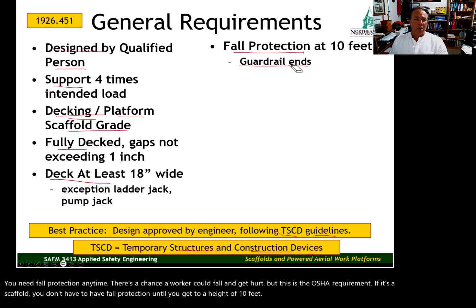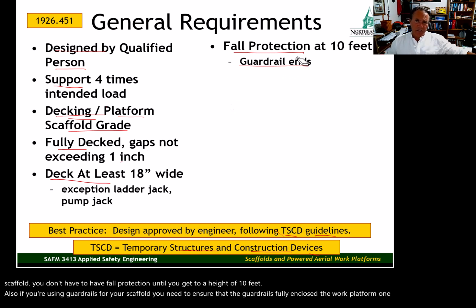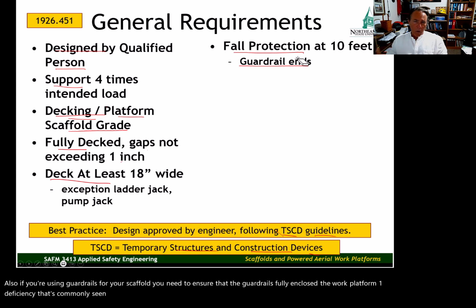Also, if you're using guardrails for your scaffold, you need to ensure that the guardrails fully enclose the work platform. One deficiency that's commonly seen is that they will only have guardrail on one side. They won't have the ends protected.